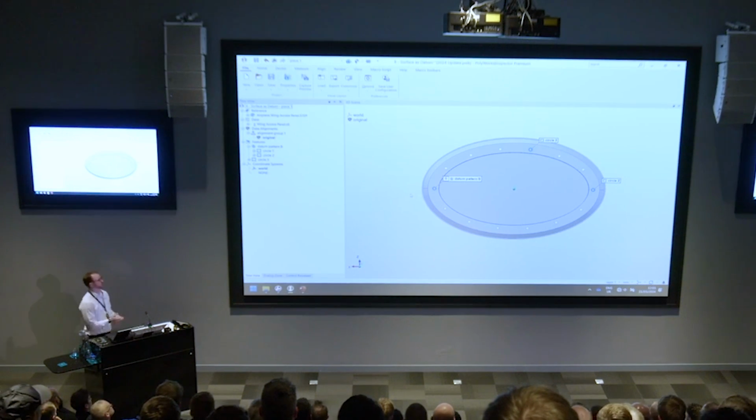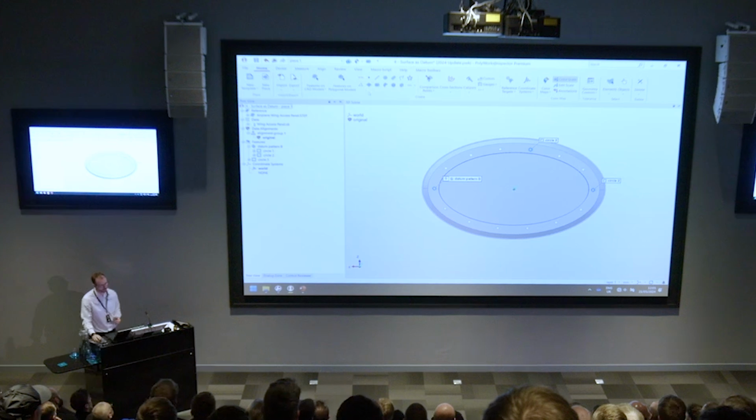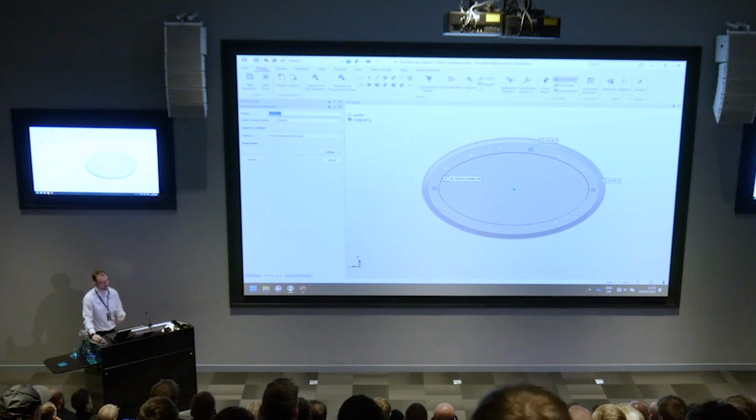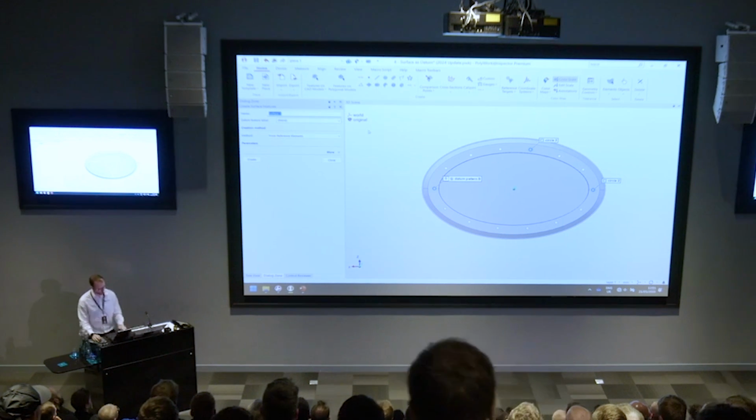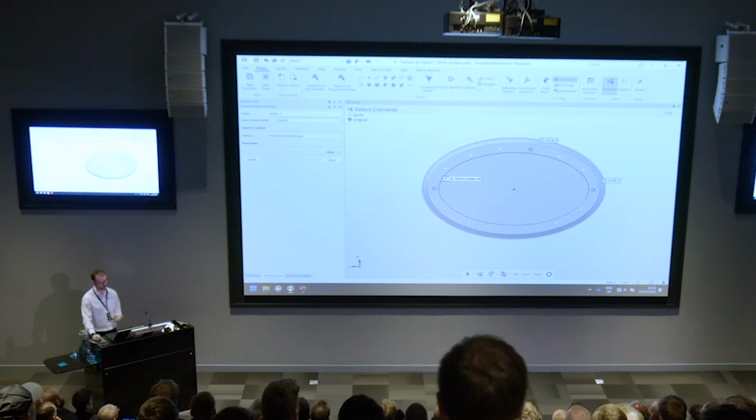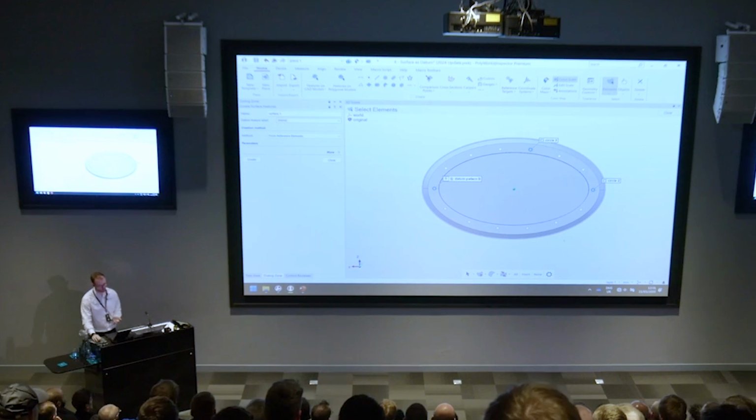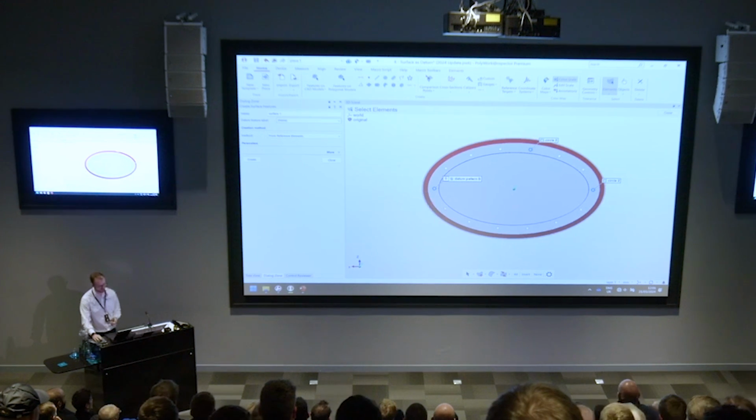Okay, so back into PolyWorks 2024. Again, just getting used to the new interface. So to create features now, you're in the Home tab, and then we have our surface feature here. For those of you that aren't aware, surface features can't be created from the actual CAD model themselves, so we need to do some manual selection. So pressing the spacebar. As Kajiva mentioned earlier, the select element options are now at the bottom of the 3D scene rather than the dialog zone. So I'm just going to choose this face here.